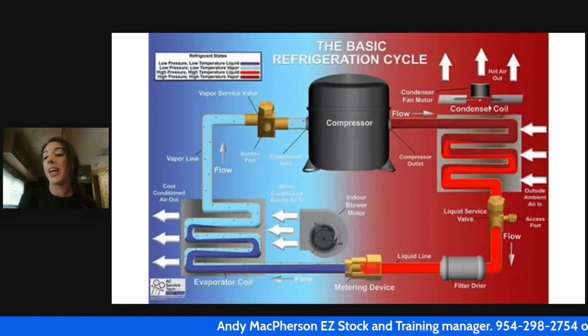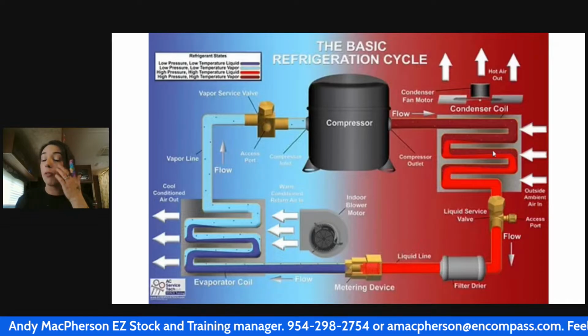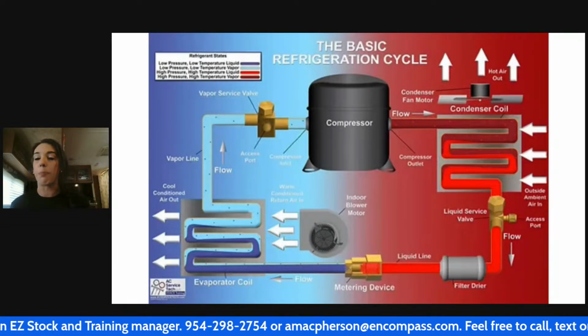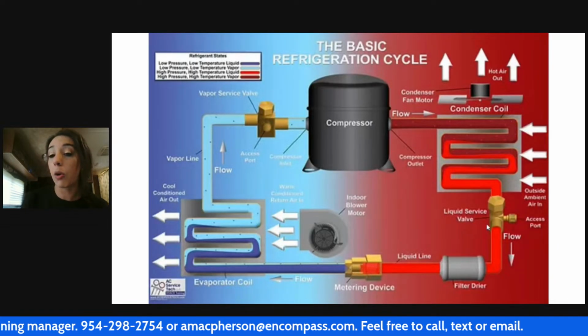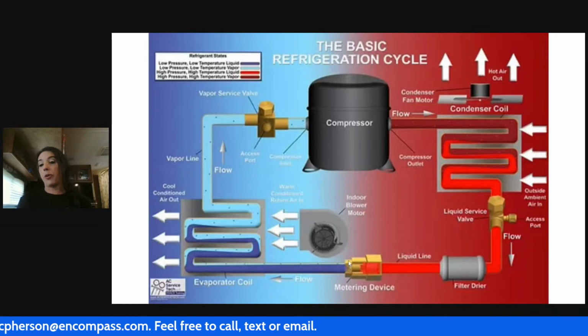So we have this fan that's helping us along. We have natural physics helping us along. And then we're moving those natural physics even deeper by having that outside ambient air cooling that refrigerant as well. So that's what we're doing with the fan on the outdoor coil.